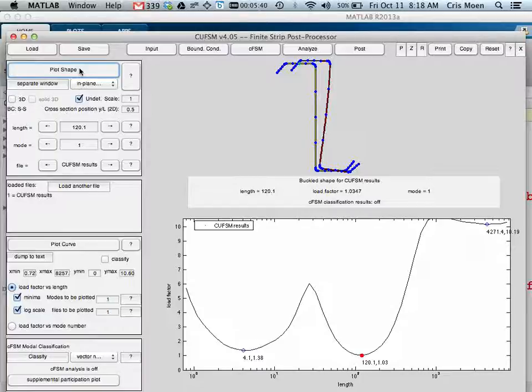2. So this is something else you have to realize, that lateral torsional buckling changes when you have these types of influences, like a lateral spring. And if you're thinking about designing bracing, you have to realize that you have 2 half waves. So if you put bracing in the middle or something, you're not going to do anything, right? It's going like this. So this also opens your eyes to things that you might not consider.